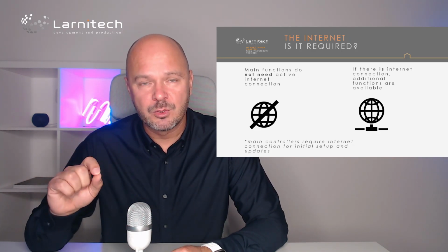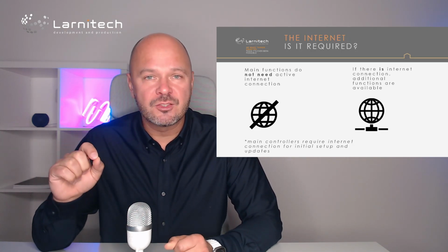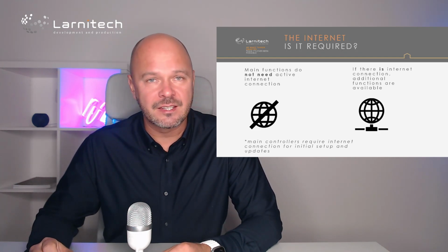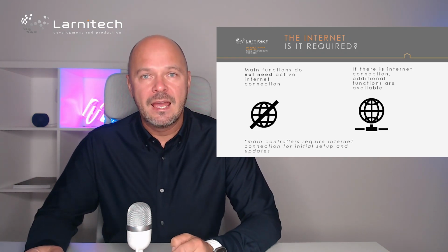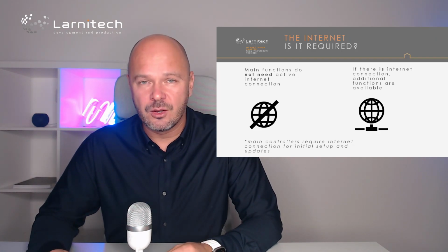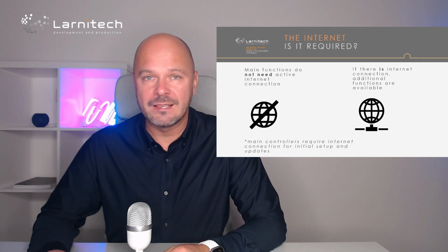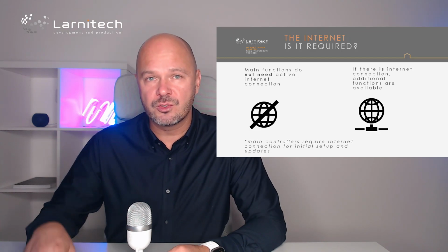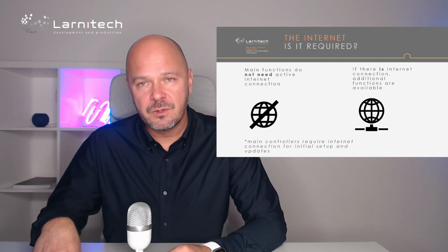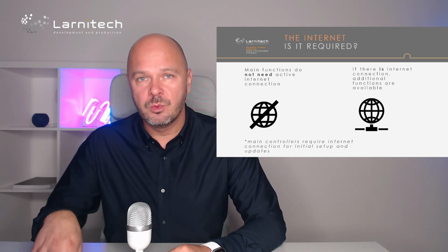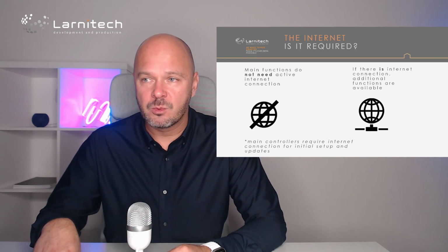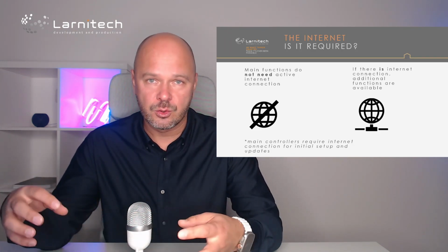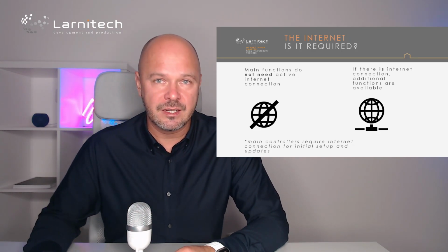Also, an important thing is that main controllers, when you first start them, require the internet connection to be updated. And there is a line of Metaforsa controllers, Cloud Metaforsa, which require internet to be set up. So if you want to change the settings and if you want additional functions, you will need the internet. But when the system is normally working, like the automation system, when devices talk to each other, they don't need the internet for this.